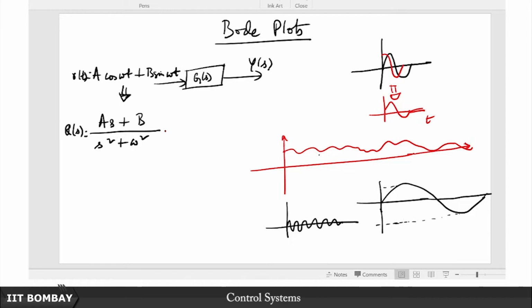So we can cook up this signal as a combination of several such different kinds of signals of all possible frequencies from 0 to infinity. That is basically what this allows us to do. Once we are able to do that for any arbitrary signal, it will be of our interest, because remember, beyond a certain high frequency it is hardly perceptible to us, because if it is oscillating very quickly, we will have these low pass filters, which will reject frequencies beyond a certain cutoff. Most control systems, most practical systems are of low pass in nature.